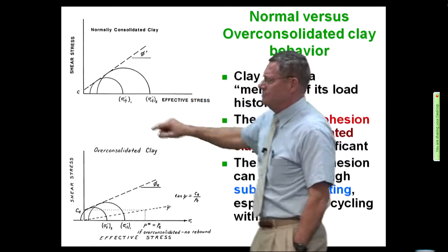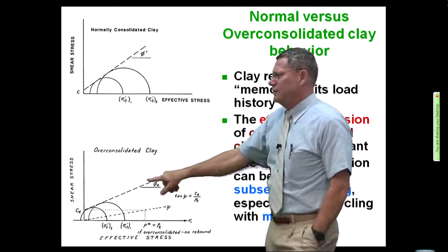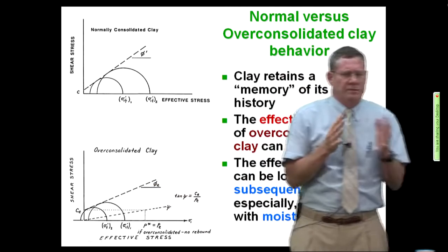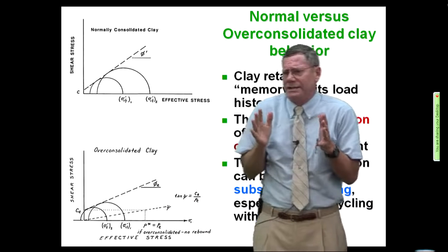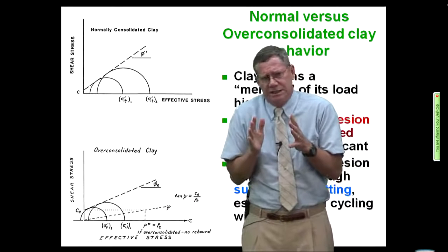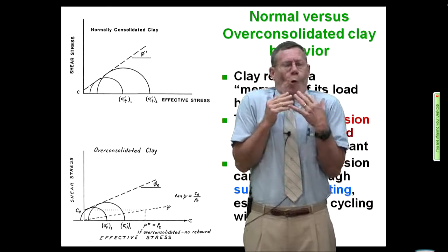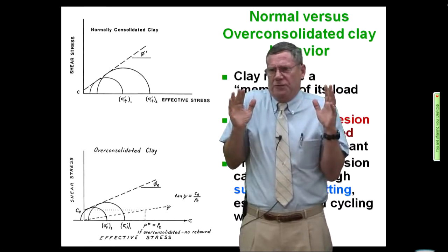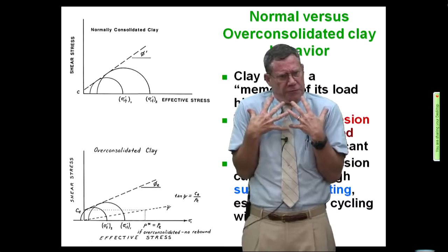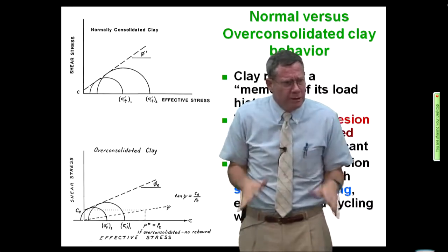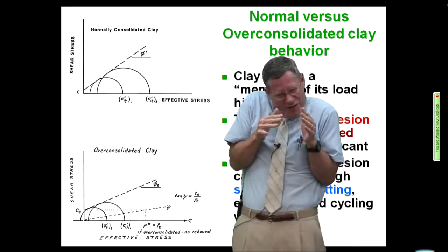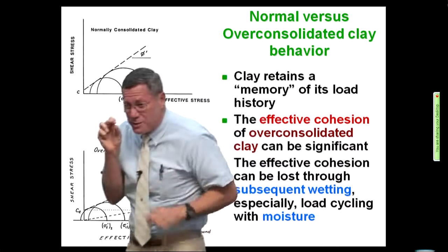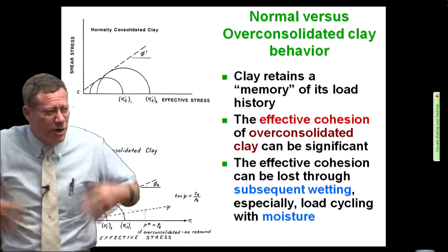It isn't that simple. And most of the time, you're dealing with overconsolidated clays. What does that mean? That's a clay that's dried out. And when it dries out, it'd be like my body dying and getting mummified. We have all these incredible suction forces as all the fluids drain out of me. And I'm going to pull tightly together. And I'm going to be a hell of a lot stronger per square inch than I was when I was filled with all this water.